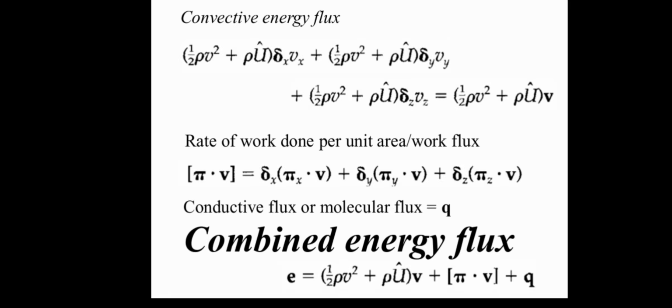The combined energy flux equation is crucial in deriving the temperature profile under such circumstances. The Brinkman number Br mentioned is a dimensionless parameter that quantifies the importance of the viscous dissipation term relative to heat conduction. In conclusion, the combined energy flux equation provides a powerful tool for analyzing energy transport in moving fluids by encompassing convective transport, energy transfer due to viscous stresses, and conductive heat flux.